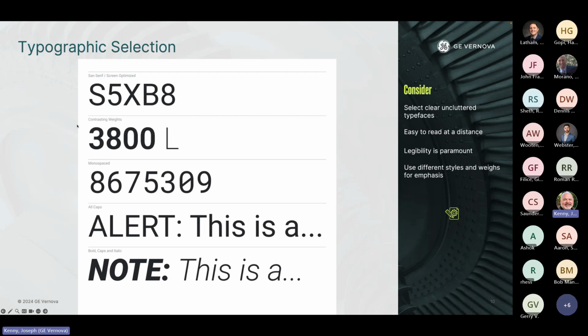It has different weights so that you can do things, and we did this in the previous HMI screen. You make the value bolder because that's most important, and then you make your measurement lighter in typeface so that once people know you're in liters, they know that probably the whole screen is in liters. Therefore, this may become less important. They only want to scan the bolder thing.